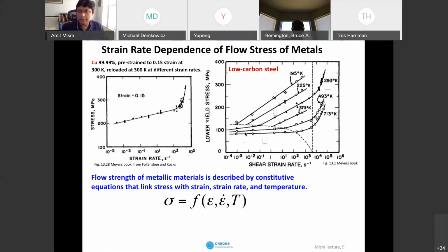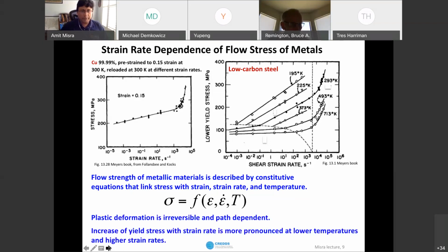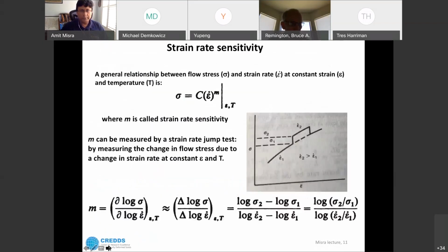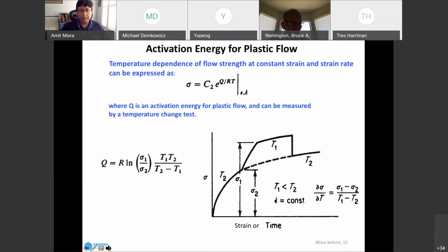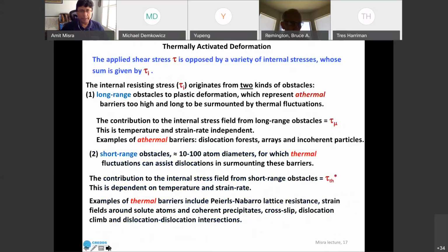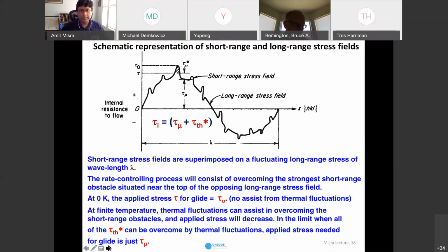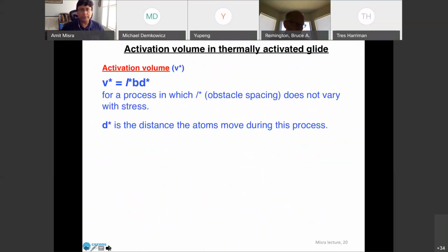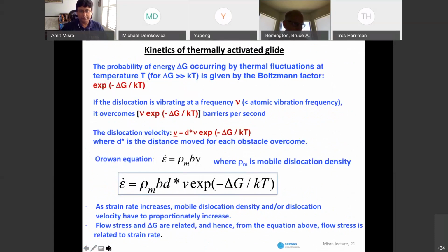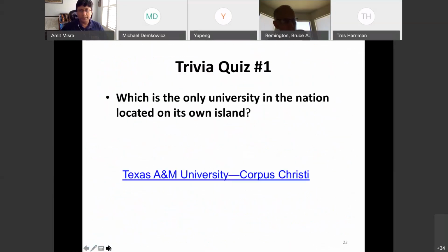Okay, and the last question here is, when the tangent modulus becomes smaller with increasing strain, should it still be called hardening, or should it be called softening? I think the nomenclature is that it's still called strain hardening, just with a lower slope. You usually have a strain hardening exponent that has some value n, maybe about 0.3. It might reduce, but the nomenclature is to still call it hardening with a lower slope.